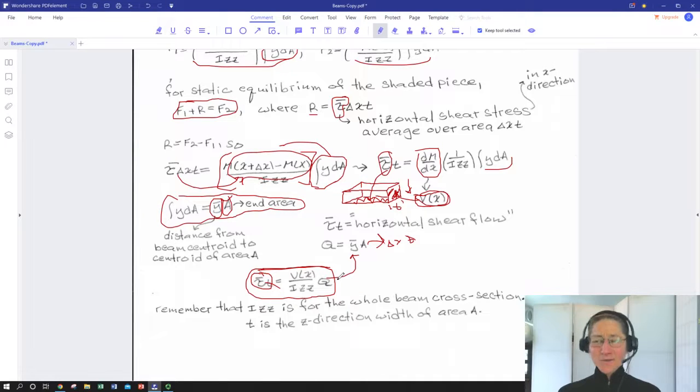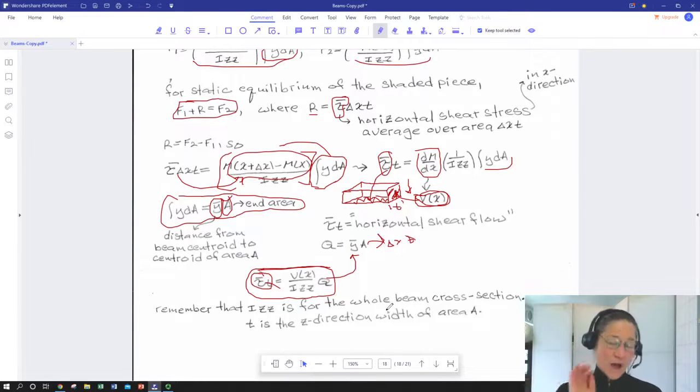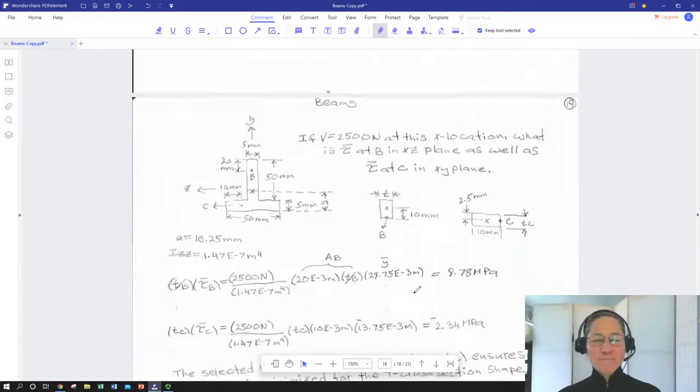So once again, as was the case for our longitudinal stress due to flexure, a bigger moment of inertia of that cross-section is going to win. And this is moment of inertia about the z-axis, so it's that same axis, not y. So basically the same kind of shapes that would have given us effectively rigidity or lowered our axial stress, lowered our deflection, it's also going to do us some good for shear, which is probably why beams are shaped the way they are in practice if you look around.